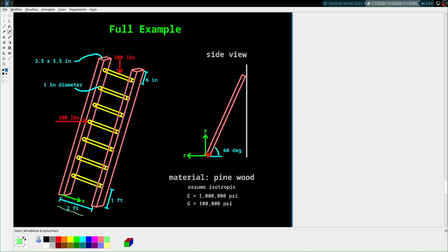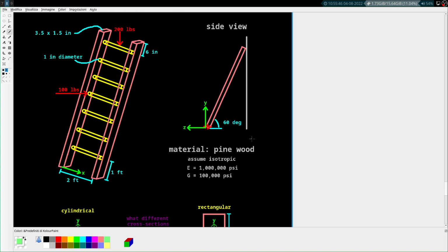So yeah, very straightforward structure here. One cool thing though, I put it at a slight angle here so it can take into account some other axes. And the bottom two legs here are fixed, and the top is up against the wall. And so we are constraining these degrees of freedom. This one is fixed in place, but this one just cannot move in this direction. Obviously, it's against the wall. It can still move in this direction, right? But it can't move in this direction.